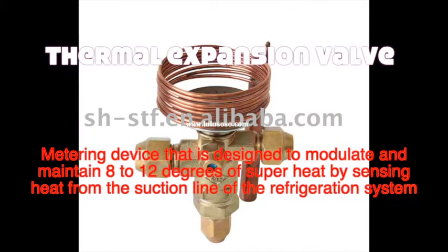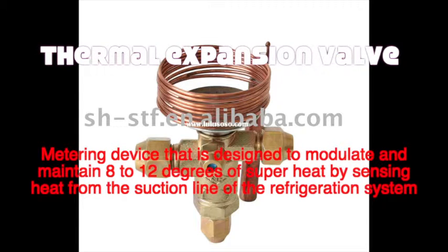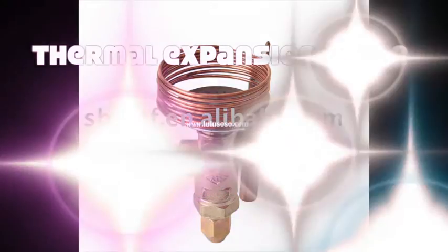Thermal expansion valve: a metering device that is designed to modulate and maintain 8 to 12 degrees of superheat by sensing heat from the suction line of a refrigeration system. That's a thermal expansion valve. Check it.